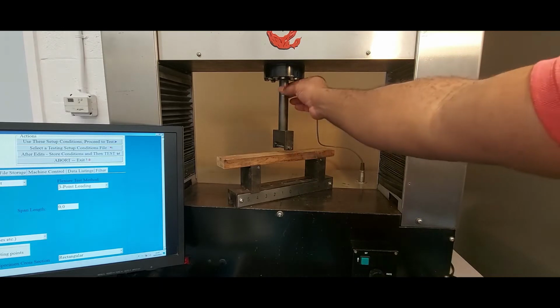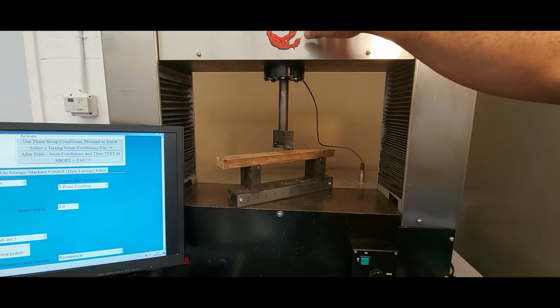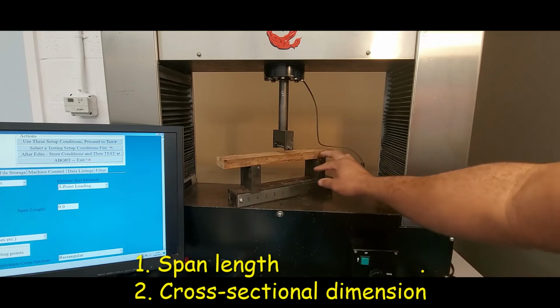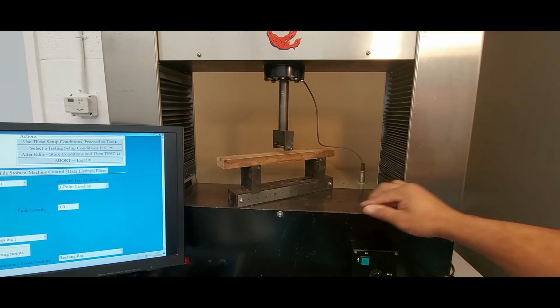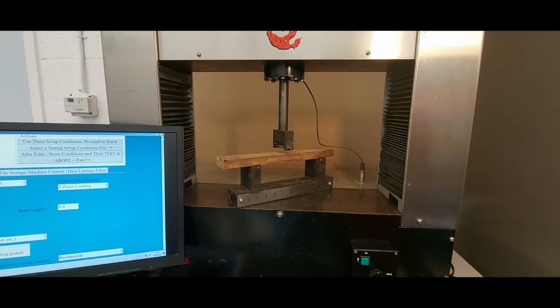with a shaft and a pin that is connected to the crosshead to apply a point load on the specimen. There are two important measurements that must be taken for this exercise. That's the span length and the cross-sectional dimension of the specimen. One should also take note of the overall dimension of the specimen.